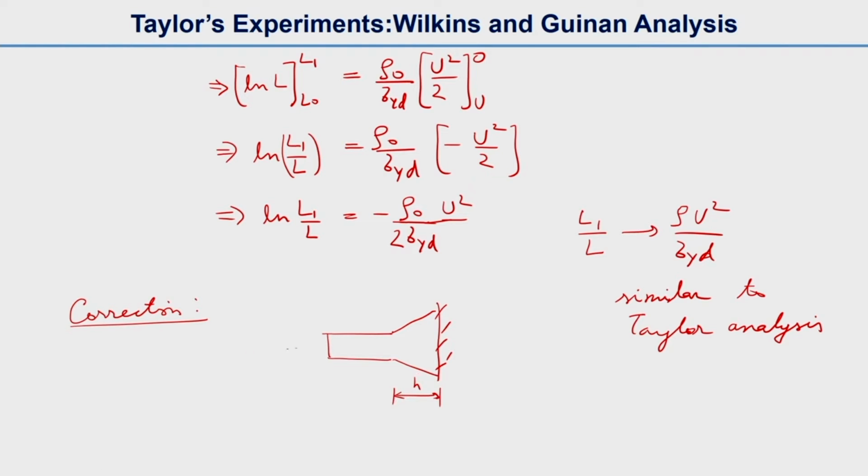When it hits first, h will increase, and then finally it reaches a fixed value of h, independent of this impact velocity u, and proportional to L naught, the initial length, or we can write h by L equal to constant.